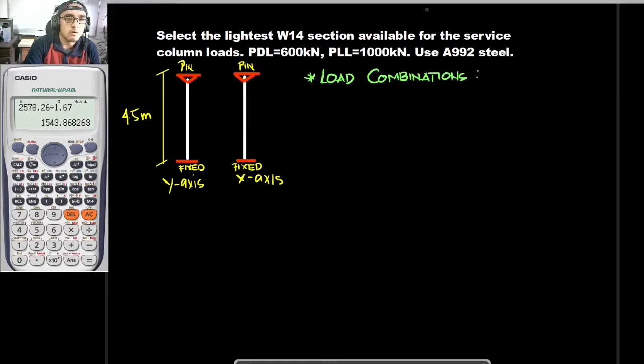Okay, so for our load combination, by the way, if you can remember what I said earlier, na kapag magdi-design tayo, it is better for us to use LRFD in selecting our sections. Then after selecting our sections with LRFD, we would be analyzing them with ASD. So with that being said, our LRFD load combinations would be PU is equal to 1.2 DL plus 1.6 LL.